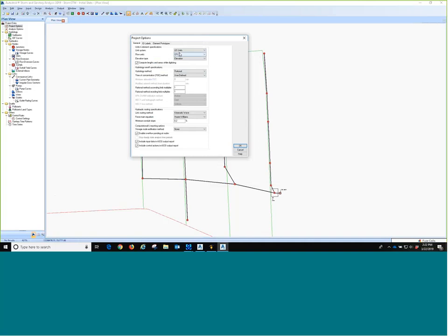So if I'm expecting, say when I double click on a junction, to see a certain list of fields available to me that I don't see, or if they're grayed out like this, what I see is actually affected by what method I've chosen. So I want to make sure that I do this the first time, right before I start anything, because otherwise everything I put in is going to be erroneous.